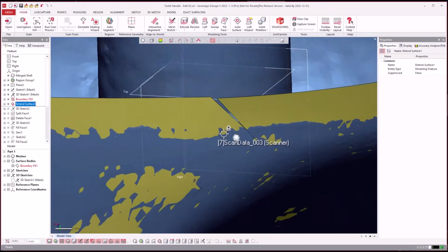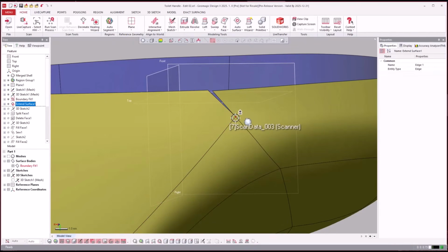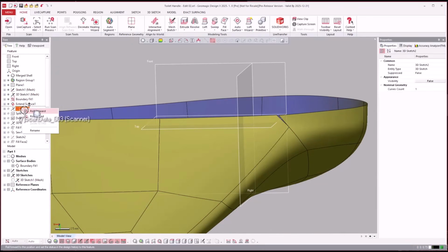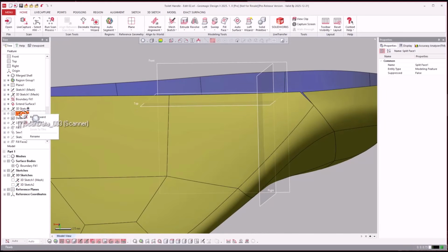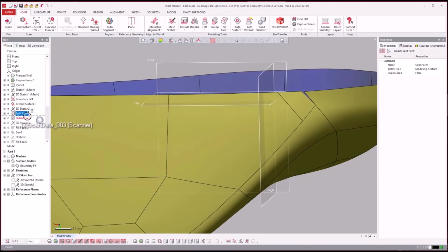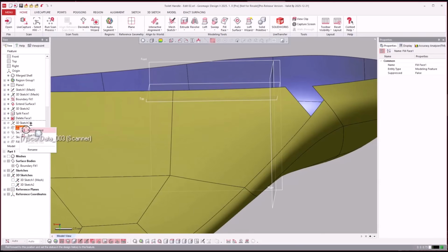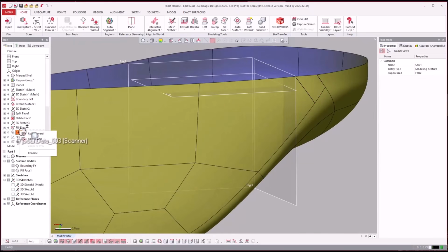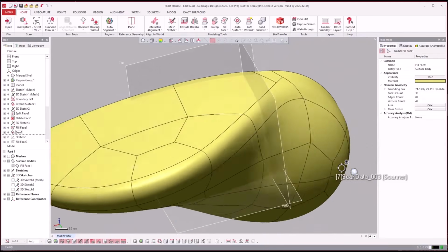Now, one thing that happened is, look at here. We extended it, and because it was coincident here, these didn't quite extend right. So rather than go around and around tweaking it, you could fix that. The quicker way would be, let's just draw a 3D sketch, split that face, delete that face, and do a fill face, and then sew it in with the rest. Nobody ever knows the difference. So we went ahead and just patched that little area.